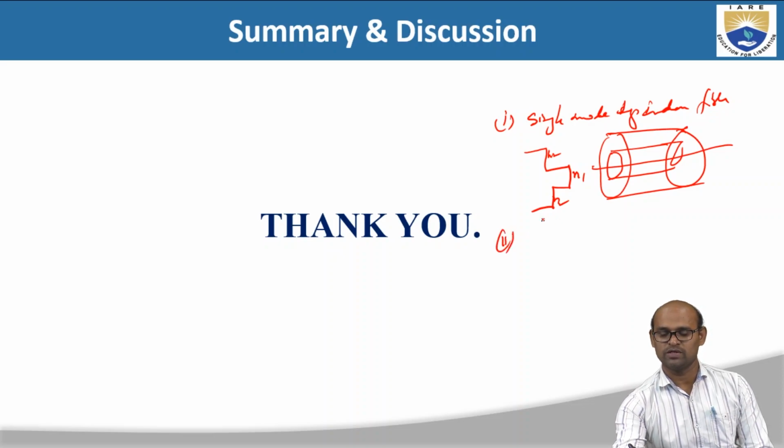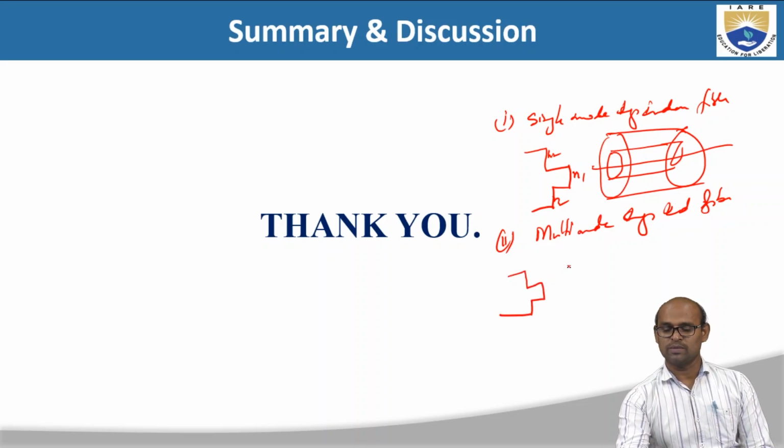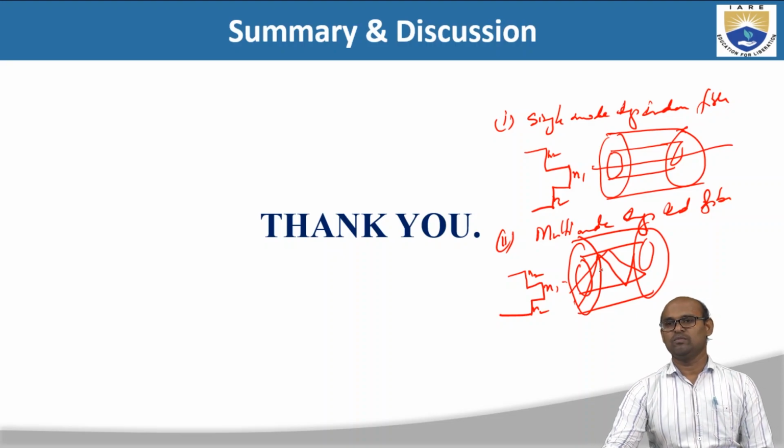The second one we have discussed is the multi-mode step index fiber. As the name suggests, it has a step index like profile. You have constant core and constant cladding refractive index. Here you don't have only one mode for the propagation, you have different modes. You can have higher order modes and lower order modes. We have discussed the propagation of light in multi-mode step index fiber.